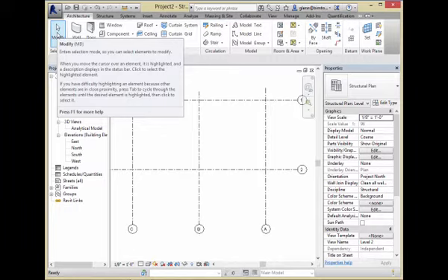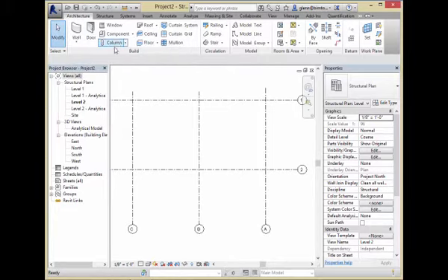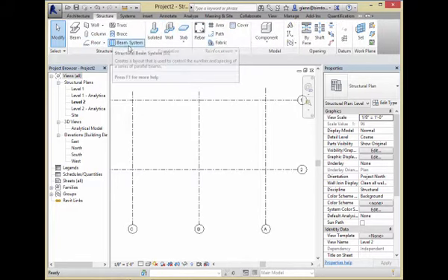Columns tend to have, if they're a steel column, a very specific profile shape that's just extruded in a direction. So the whole steel catalog is out there, all the detailed profiles of exactly how thick the flanges are and how big the web depth is. That's all available. But when we're placing columns, you go to the Structure tab. You choose the Column tool.